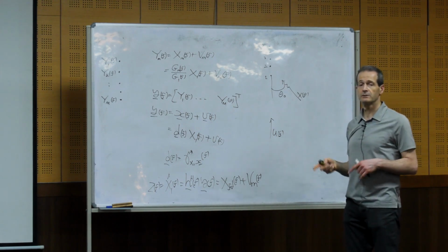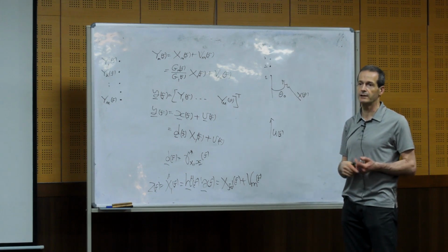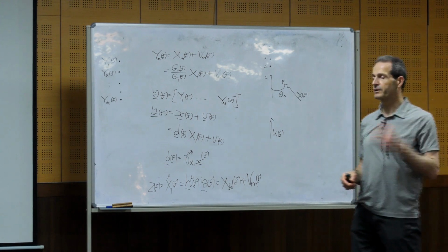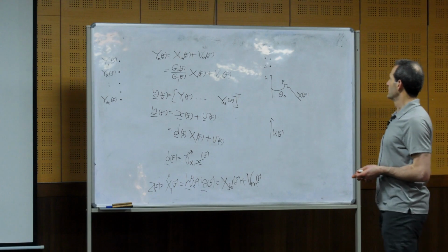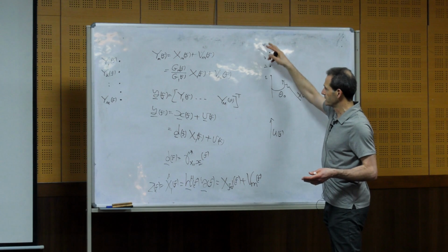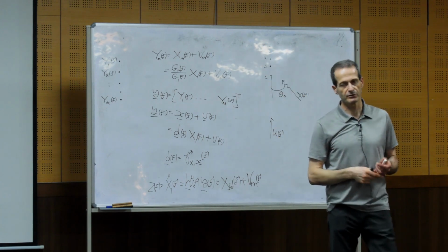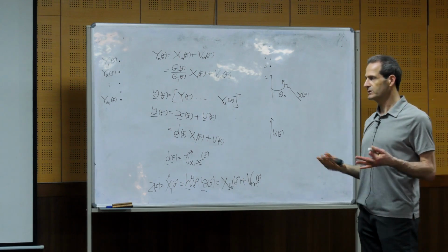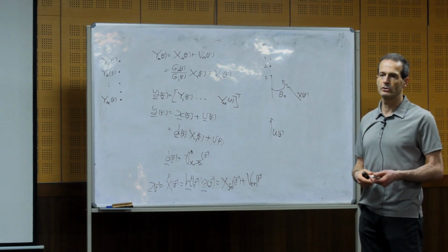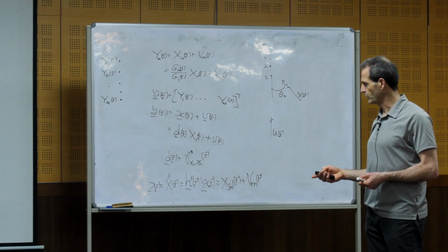Not too much, based on the number of sensors. The power will be reduced inversely proportional to the number of sensors, which means that we reduce the noise by the square root of the number of sensors. So we can reduce it, but it's not much. We need many, many sensors in order to average the thermal noise if they are independent. So let's see what happens.